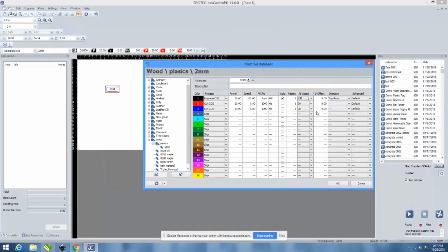John, can you just touch on why it's important to have on for cut? Yeah, most materials, if you don't have it set to on, well, there's 2 things. First of all, your material may flame up, so that's certainly the case if you're trying to cut engraving plastic or acrylics or rubber. The second thing that's important is to make sure it's on to protect the lens.